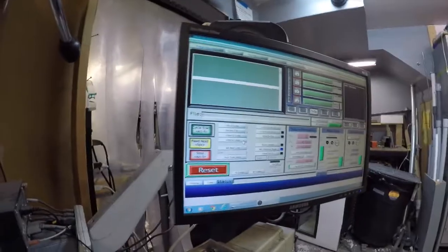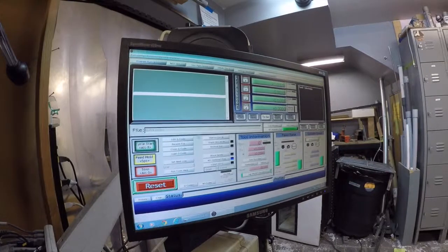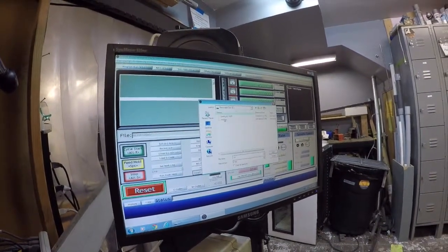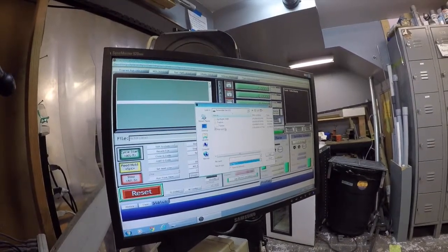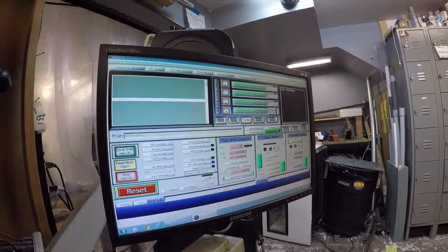Now if you imagined thousands of those, in fact the project that I'm going to try and run right now is about 75,000 lines of coordinates like that. So here you can see I have this option, load G-code. So let's click that, and I'm going to go into a removable disk that I have. There's my thing, logo.gcode. I'm going to load that up.